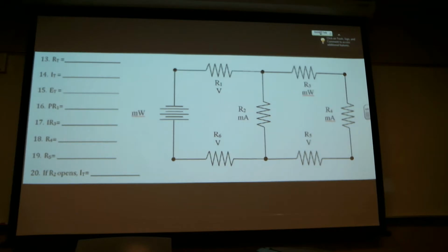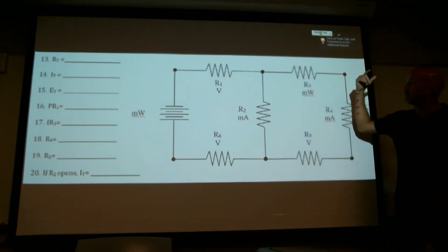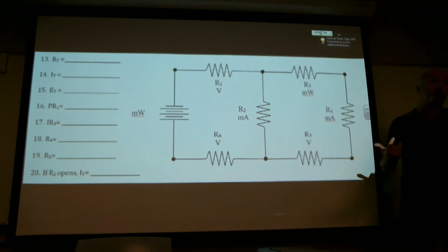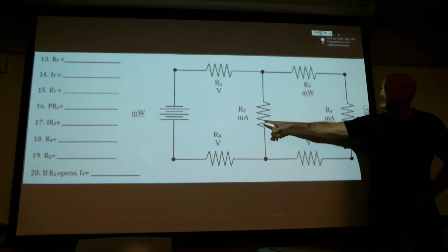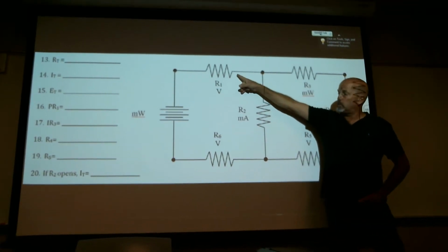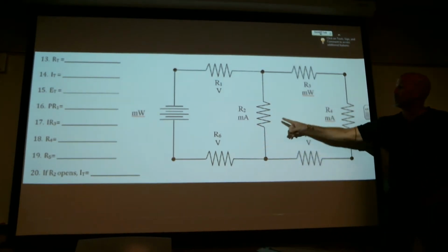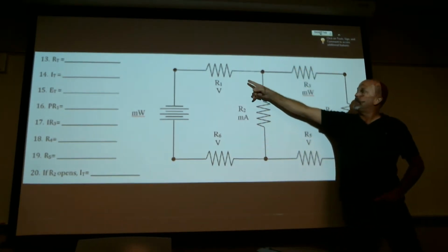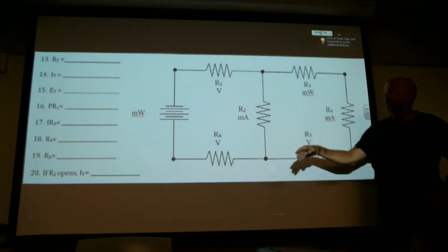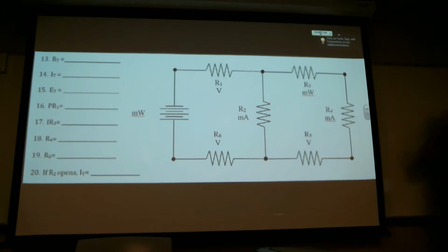And then you have this one. It is mixed, it's not all parallel, but you just did one of these. You guys all did quite well. But you've got a current on this path and a current on this path. You've got R1, which is out by itself, and R6 out by itself. So once you add these 2 currents together, you've got your total current. And these 2, R3 and R5, share the same current as R4. So right off the bat, you've got all your currents.